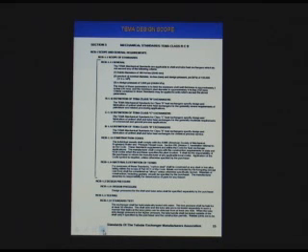Just about anything you want. You can use carbon steel, Incoloys, Hastelloys. We just got into an issue on that, which there are many ways to apply a clad. You can either use a roll bond clad, or you can use an explosive bond clad. On explosion bonding, they will basically put the alloy sheet on top of a carbon steel plate.